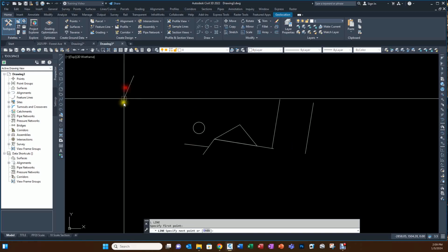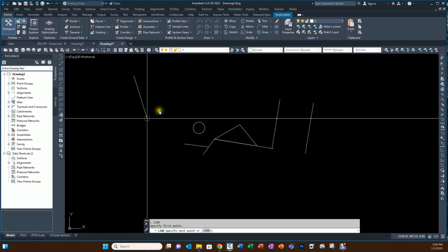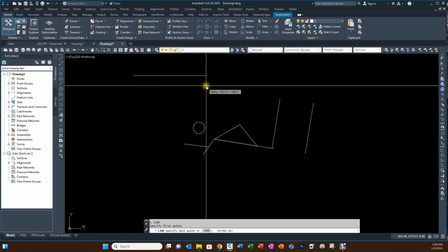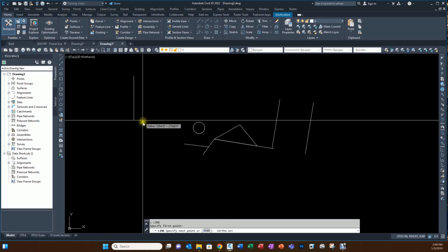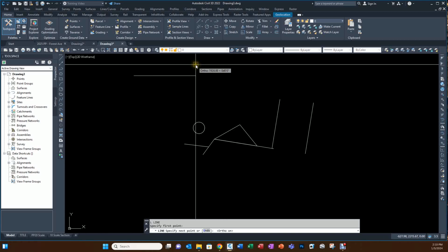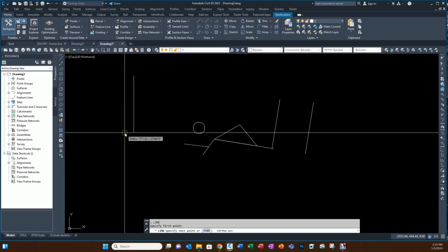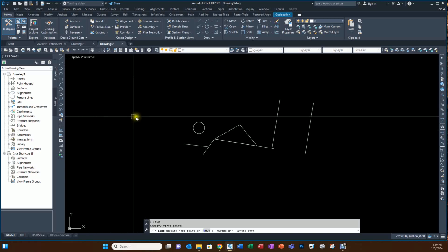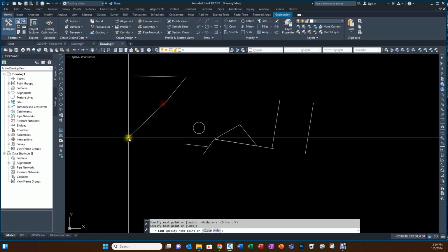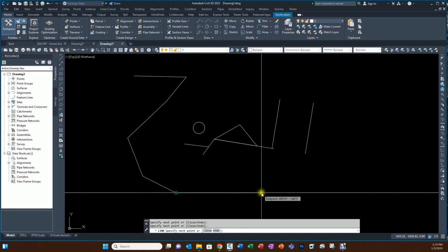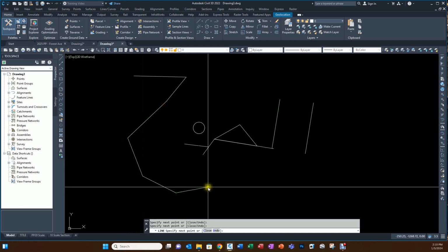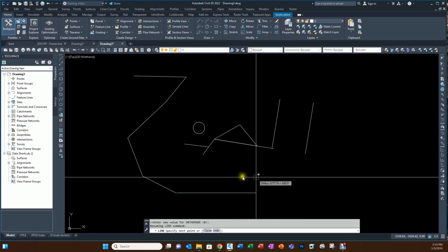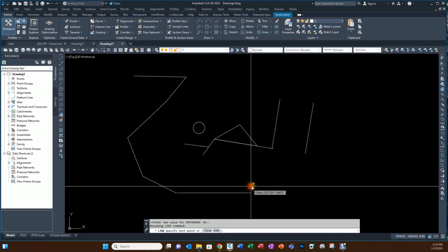If you're drawing lines, you see this will rotate anywhere you want. If you press the F8 key, now it's in perfect ortho mode, so it'll only be at right angles, either completely horizontal or completely vertical. If you're doing a one-off, horizontal or vertical, and you're kind of cooking, and you get to where you want a perfectly horizontal line, I can hold down the shift key, and it's just kind of a temporary ortho mode.